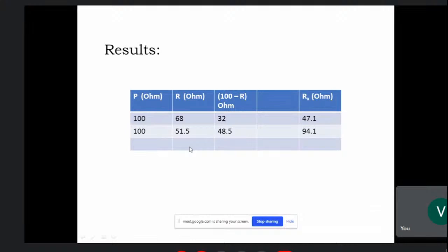Since it is a 10 turn pot, your sensitivity goes very high. You can actually measure with 0.5 ohm accuracy. This is not easily achievable with so expensive a potentiometer. I don't know why universities always suggest these huge instruments, and this is easily available nowadays. 10 turn pots, even 100 turn pots are also available. This is cheaper. If you go to higher turns, then that becomes very expensive. This is within our range, about 200 rupees, nothing.